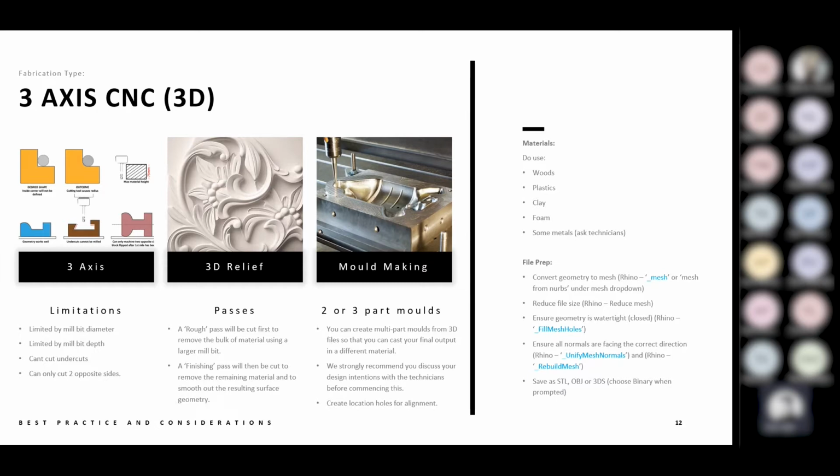In which case, making a nice solid mold, something like this, you could carve it out. You can make little locating pins or locating holes so everything aligns nicely. You'd allow a little hole to pour a material into it, and then you've got a reusable mold, which is fantastic. So you CNC it out of something tough like Necuron or some form of metal like aluminium, and then it's just a case of pouring in things like your concretes, your plastics, so things like injection molding you could do with it. There's so many applications that you can do by combining these machines together.